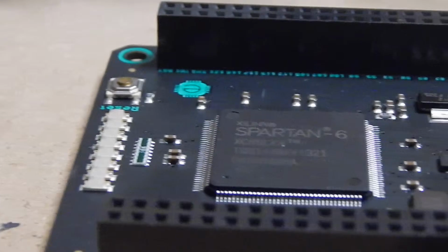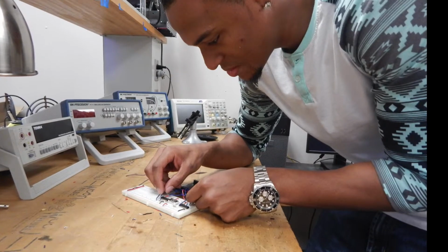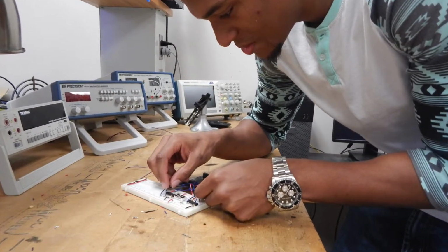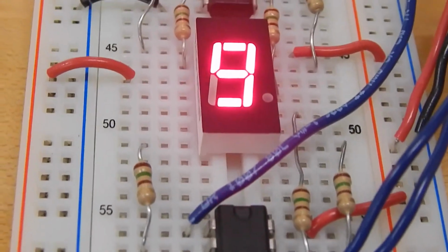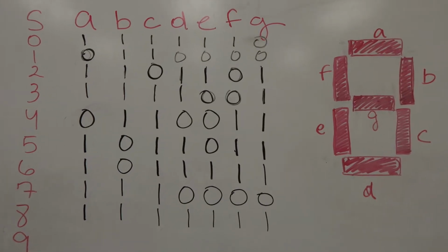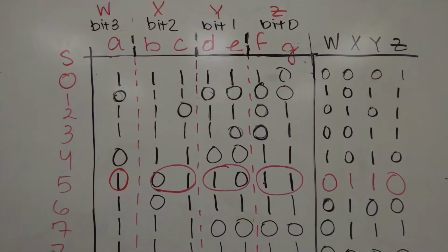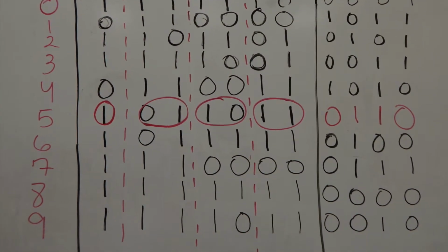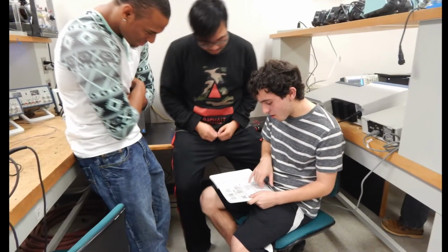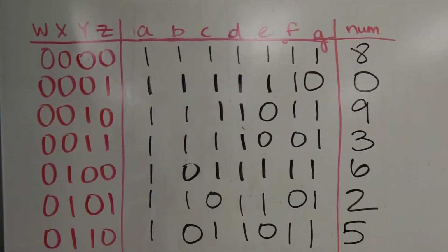Field programmable gate arrays are semiconductor devices with a hierarchy of reconfigurable interconnects that allow the blocks to be wired together like many logic gates that can be interwired in different configurations. In this lab, we use two theories for three subsystems. The first one is we use the flip-flops to store the bits of the data, which are binary digits, and change states to verify the 4-bit inputs for 7 segments. The second one, we use the K-maps to simplify the truth table, which shows the binary digits of numbers from 0 to 9.